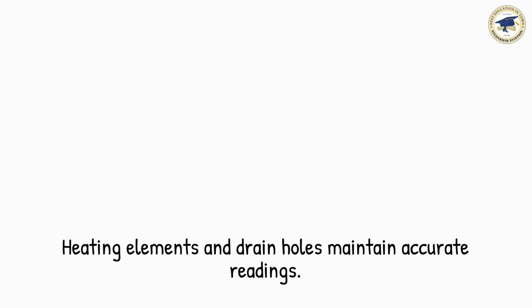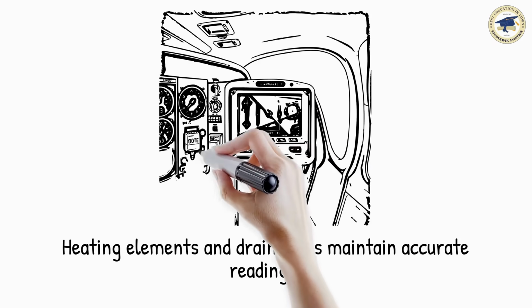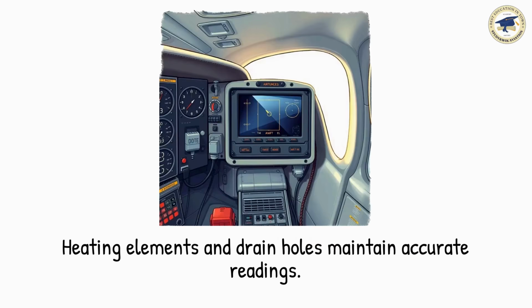Pitot head measures pitot pressure. Static head measures static pressure. Pitot-static head combines both in one probe. A heating element prevents ice. Drain holes let out water. Both are calibrated to keep readings accurate.